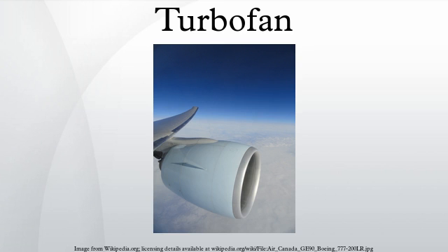Modern low-bypass military turbofans include the Pratt & Whitney F119, the Eurojet EJ200, the General Electric F110, the Klimov RD-33, and the Saturn AL-31, all of which feature a mixed exhaust, afterburner and variable area propelling nozzle. High bypass turbofan. The low specific thrust, high bypass ratio turbofans used in today's civil jetliners evolved from the high specific thrust, low bypass ratio turbofans used in such production aircraft back in the 1960s.